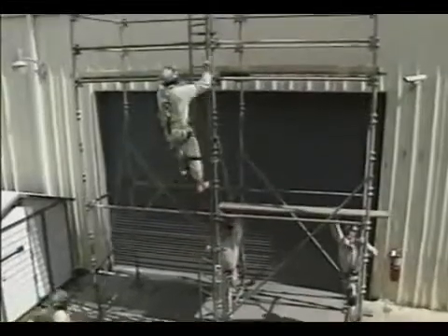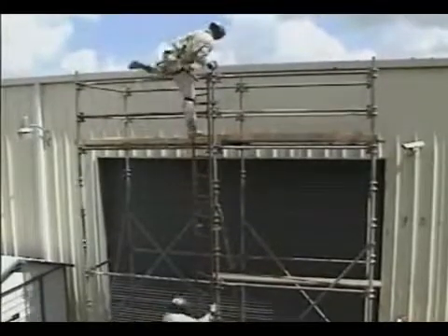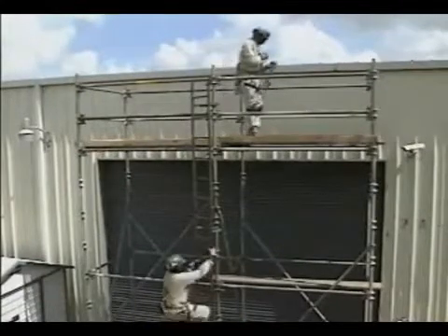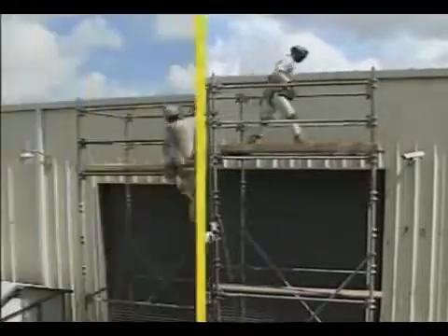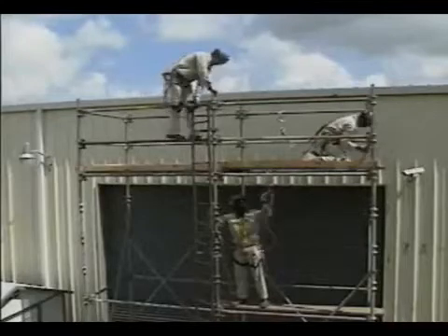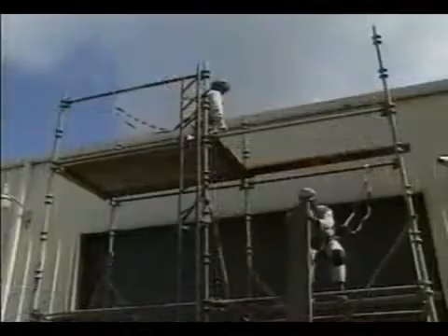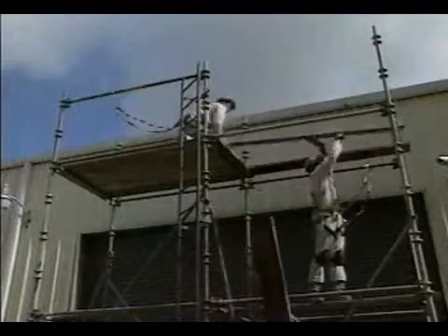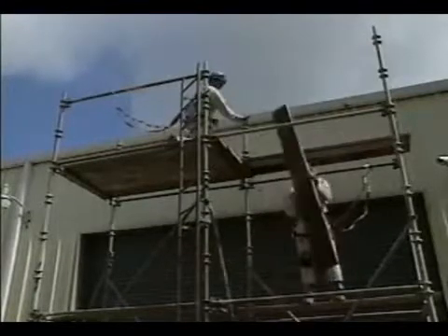For example, always use both hands when you're climbing a scaffold ladder, and be careful when you're entering or leaving the work platform. Don't jump onto the scaffold flooring, since there's always the possibility that a plank could be loose or break. Also, avoid overloading a scaffold. Always follow the manufacturer's recommendations about safe working load limits. Finally, never use ladders or makeshift devices on top of a scaffold to increase the height of the work platform. If you need more height, add on to the scaffold.